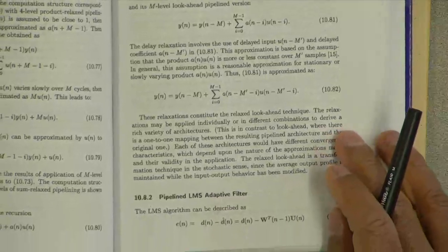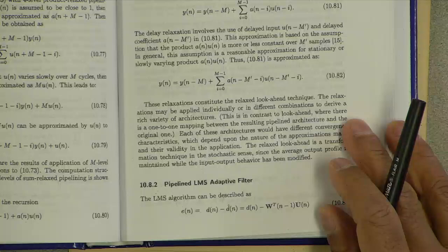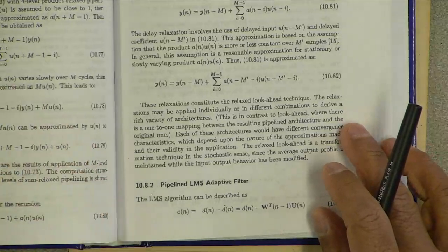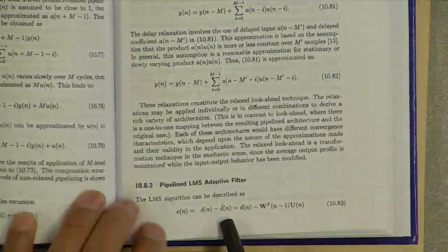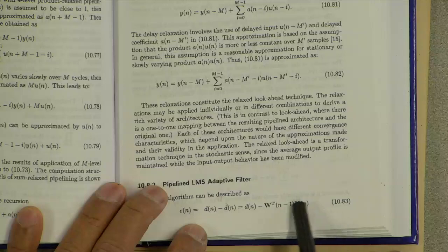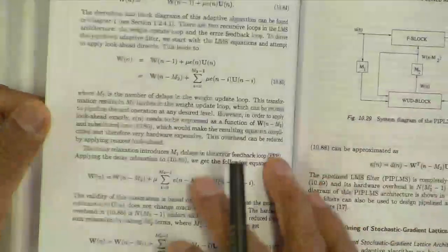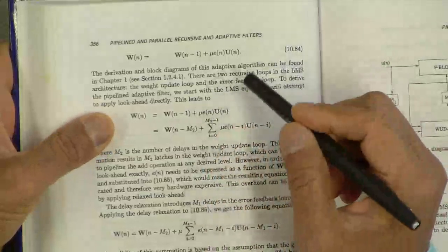So if we take all these three ideas that we have talked about and apply that to the least mean square adaptive filter, the filter equation here is e_n equal to d minus d hat, the desired estimate, which is d minus the filtered output, the inputs filtered by that weight w, and that w is being adapted by the least mean squared algorithm.